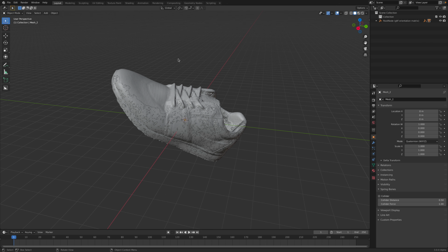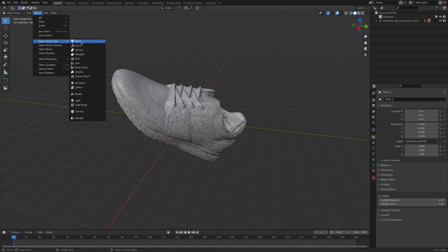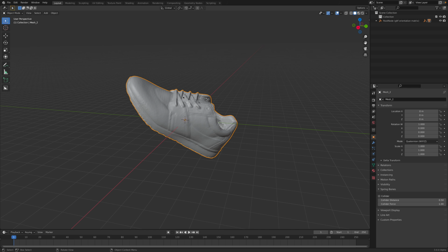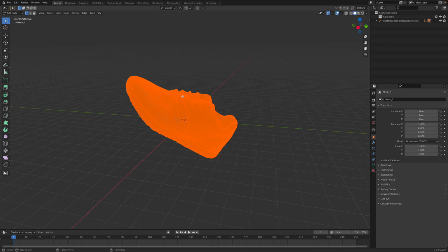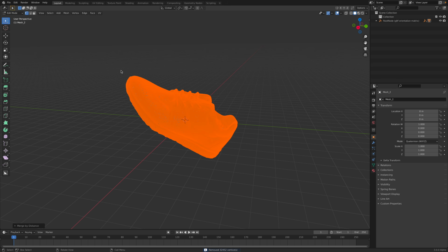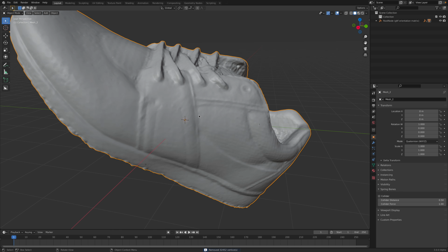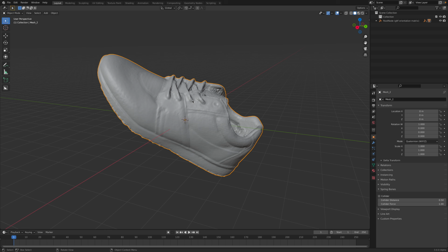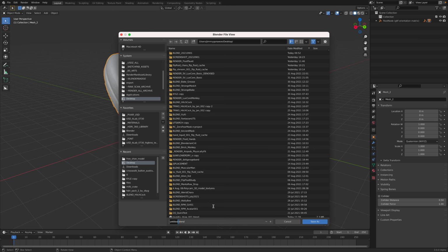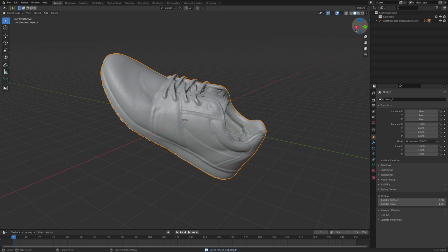Most of the time you want to select all by type mesh and then Command J, join all of them, and then hit tab, right click, merge vertices by distance. Now it's cleaner, and you can see this is quite dense and high resolution. You can keep that, but you want to also maybe decimate just to keep it less heavy for your computer.